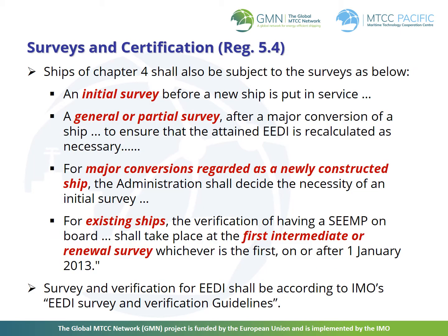Ships in Chapter 4 are also required to be subject to the surveys as below. An initial survey before a new ship is put into service, a general or partial survey after a major conversion of a ship to ensure that the attained EEDI is recalculated as necessary. For major conversions regarded as a newly constructed ship, the administration shall decide the necessity of an initial survey. For existing ships, the verification having a SEEMP on board shall take place at the first intermediate or renewal survey, whichever is the first, on or after the 1st of January 2013. The survey and verification for EEDI shall be done according to IMO's EEDI Survey and Verification Guidelines.